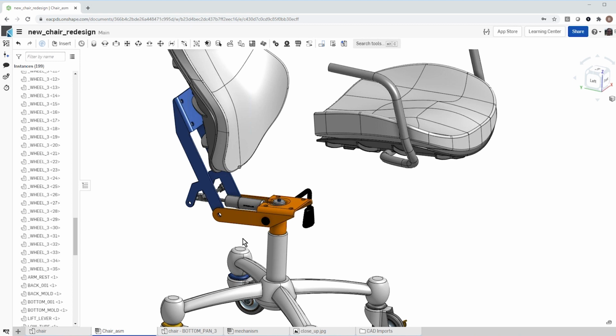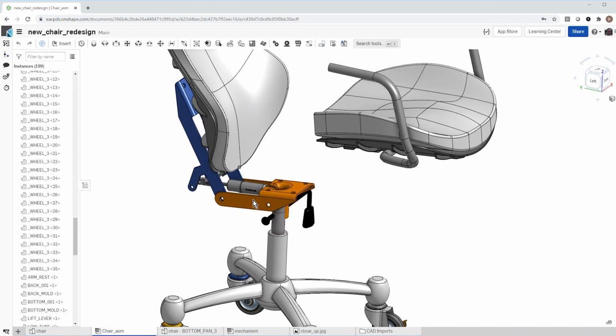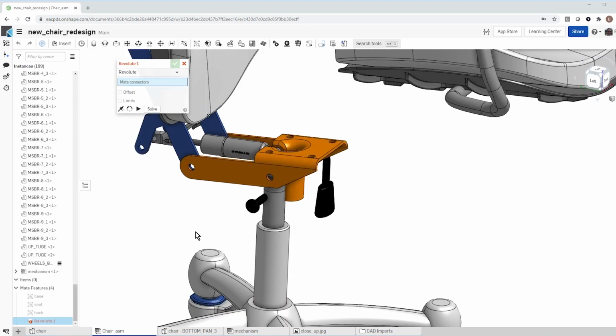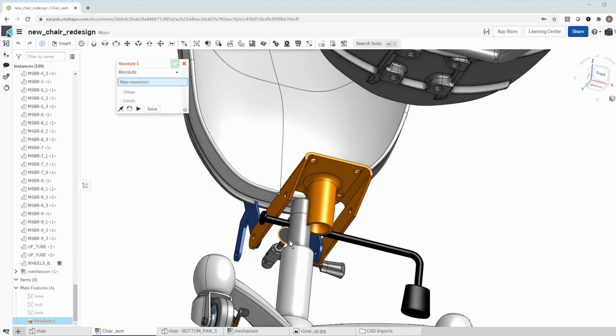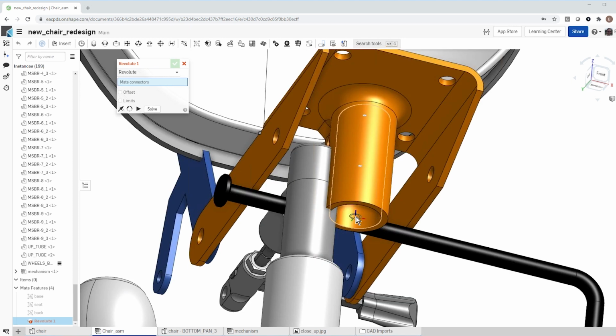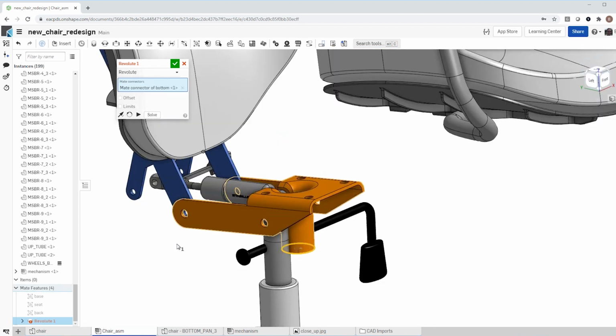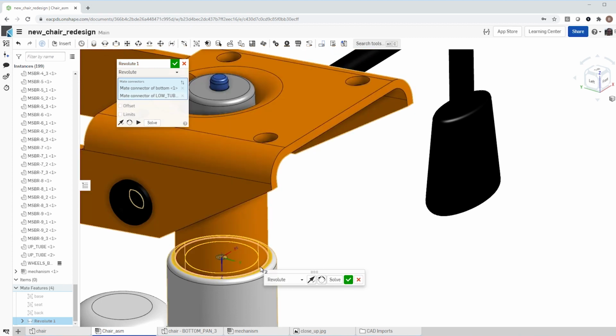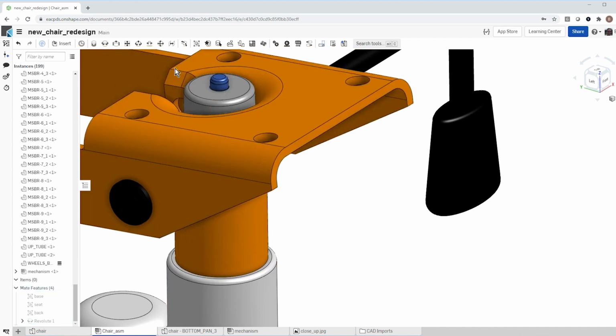because we want to be able to swivel the chair and also lean back on it. So I'm going to pull this up a little bit. And I'm going to assemble him on here again with a revolute joint. So that's going to allow the chair to rotate, this guy with this guy right there. So now he's there and now he can rotate.